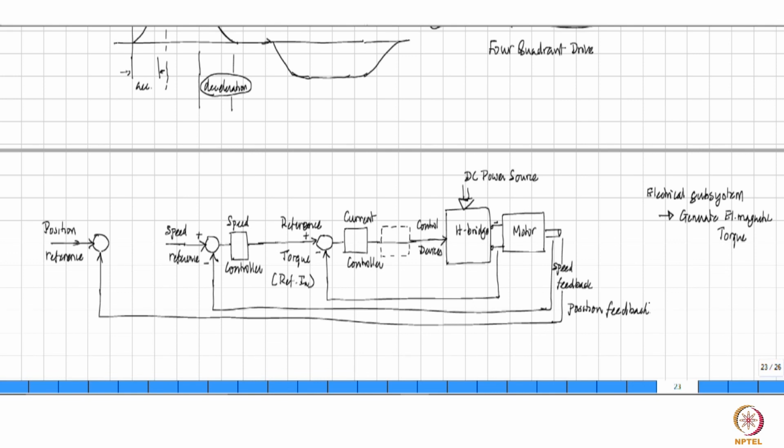Note that even if you are looking at a robotic arm which is going to take an object, move it in space and then put it down somewhere, the entire motion of determining where the object is at a particular location in space at a particular instant can be equivalently mapped back to the position of the motor shaft, because the motor shaft is what is going to cause rotation. The motor shaft linked with certain mechanical linkages is going to result in the motion of this object, and therefore you can map that back to the shaft angle, and that is what this motor control system will see.